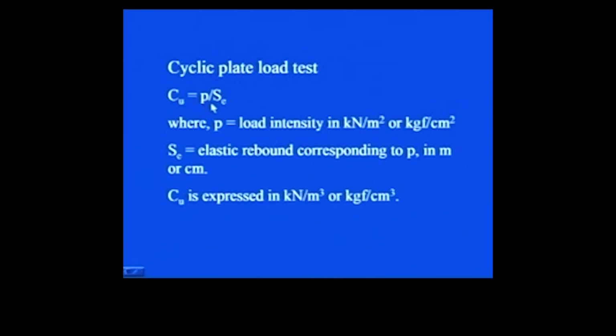So here you see that Cu was the coefficient which we intended to find out, is equal to P by Se, where P is the load intensity in kilonewton per meter square or kg force per centimeter square. Se is elastic rebound corresponding to P in meter or centimeter. Then your unit of Cu will be kilonewton per meter cube or kg force per centimeter cube.